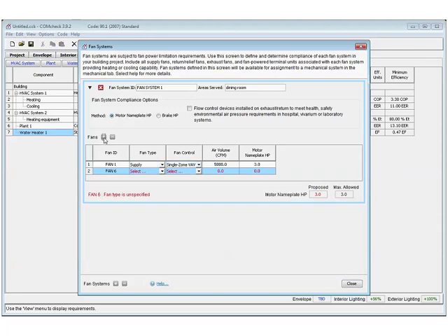So I'm going to add, I hit the plus sign. Let's put in my return for this fan system detail. I will come over and I'm going to select single zone VAV. Return, put 3,000 in there. I can tab or hit return. I hit the tab button.